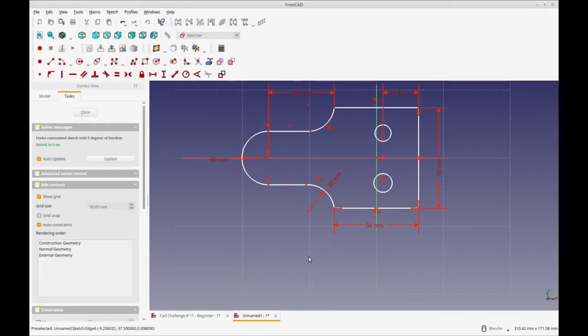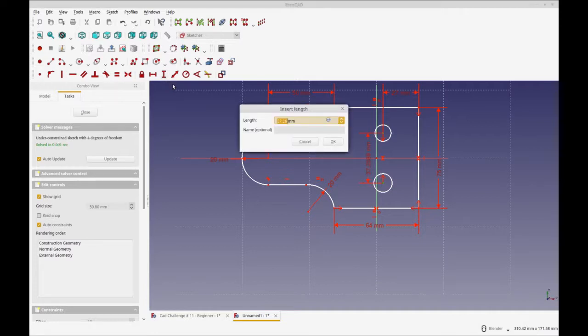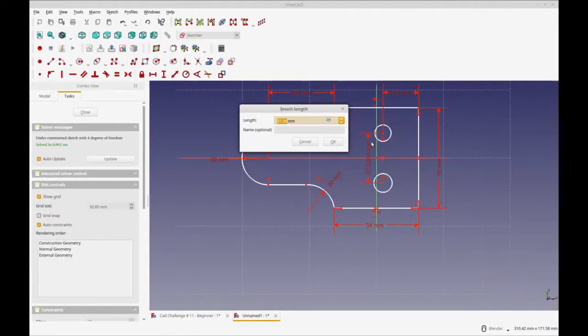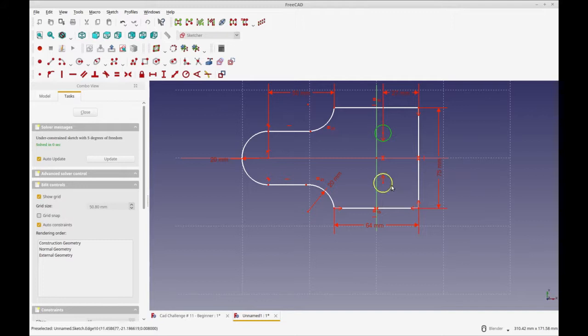And that's the final distance of our holes, and now we give them a distance to separate them. The measurement from edge to edge was, okay, so you see it's there, 34 from edge to edge, but I don't want to do a construction geometry. I could do a construction geometry there, but it's going to be 34 plus 10, because these radiuses are, oh, I'm sorry, let's set the radius first so we know that.